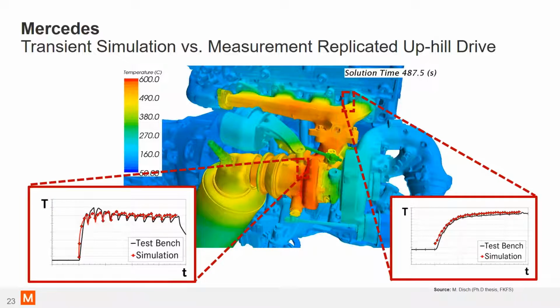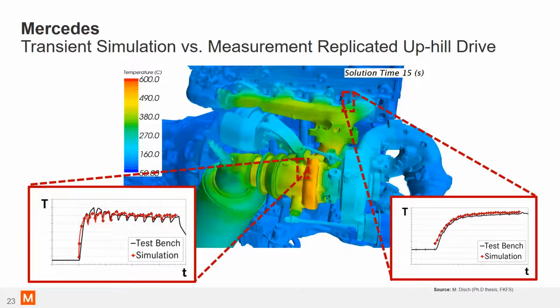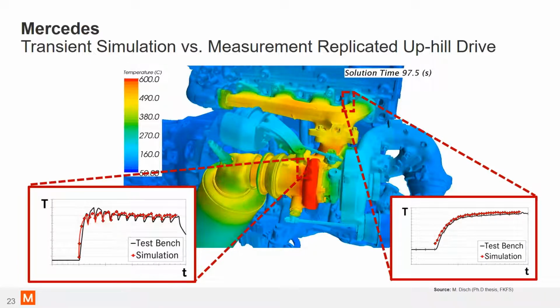We are looking at the peak temperature versus time. During the transient case, we can pick up critical zones when and where they occur and which components exceed their critical max operating temperatures. While tests can provide around 300 points, in simulation we can have unlimited number of probes to record the data and understand the behavior of components to various load conditions.